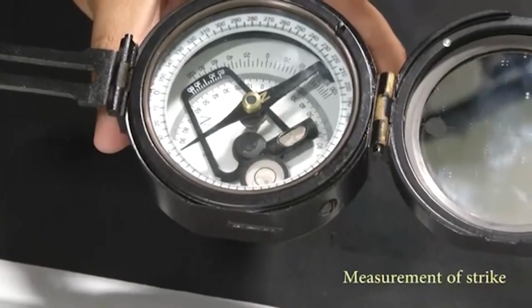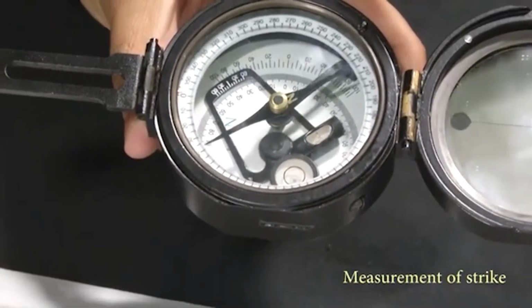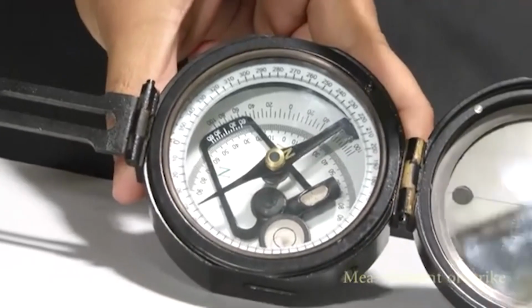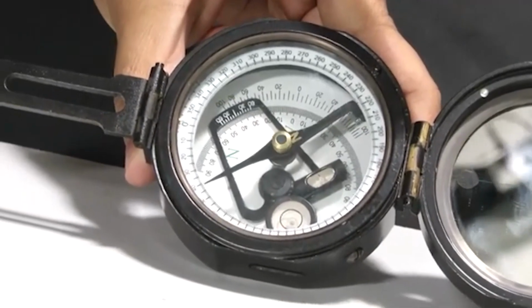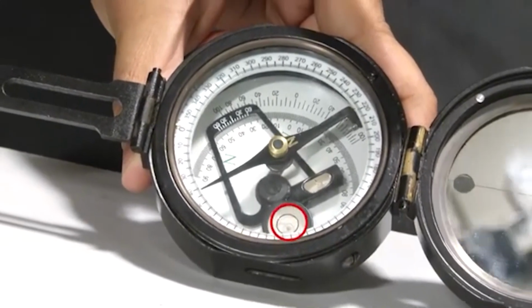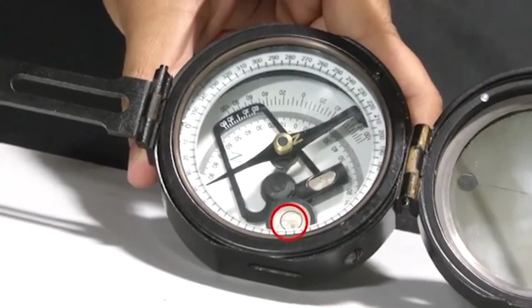Now to measure the strike, we place this basal edge of this compass against the plane we want to measure. Once we do this, we have to make sure that the compass is in horizontal position. The horizontality of the compass is ensured when we know that the bubble in the circular level is in the center, which is now the case.